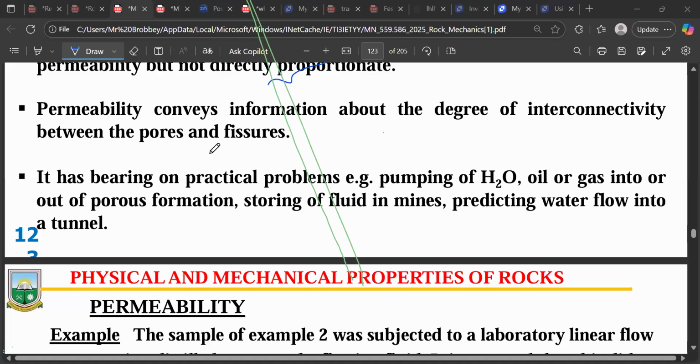I wanted to verify something on what he said. As my brother just said, it depends on the explosive or the chemicals you are going to use. Sometimes, either with water or without water, if you are using emulsions and other stuff, you can still blast. But in terms of blasting and drilling, we at least try to pump the water out or accumulate the water at one section so that it will reduce and prevent caving of the hole. If the hole caves and you pump in the explosive, it won't get to the charge and everything will affect the blast.